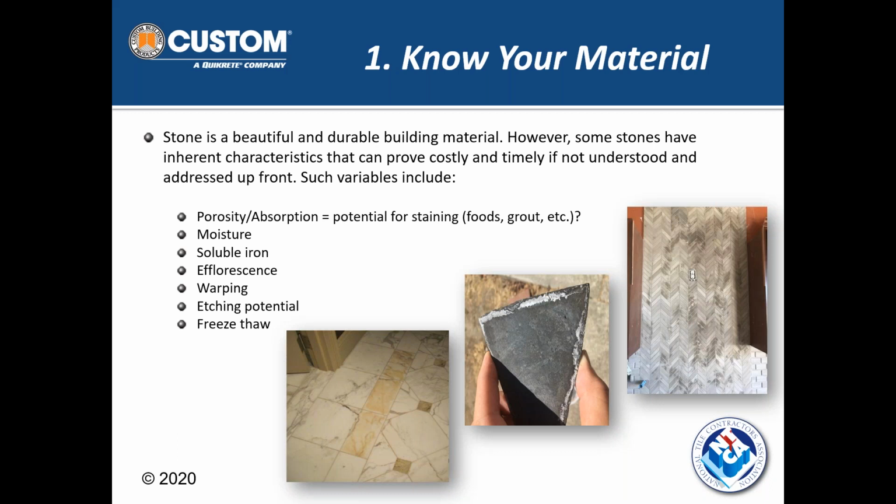Is the stone going to warp? And what is the potential for etching, a freeze thaw? Is it suitable for different climates where that could be an issue? Some limestones or some sandstones work great in freeze thaw. Others will completely blow apart, spall, and deteriorate just within the first few freeze thaw cycles.